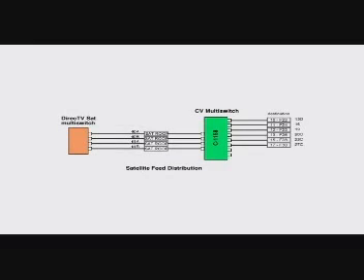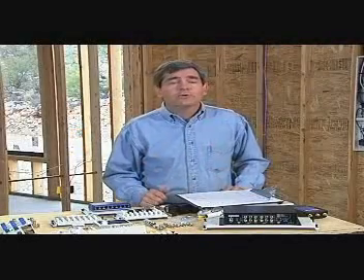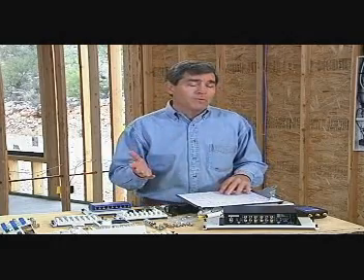We also designed the satellite signal distribution. This operates independently from the rest of the RF distribution system. We chose to provide up to 8 satellite receiver locations by incorporating a multi-switch that operates with a DirecTV 3LNB dish. Now we'll take you through more of the design details of the system, including the channel plan, in Part 4 when we install and configure the system.